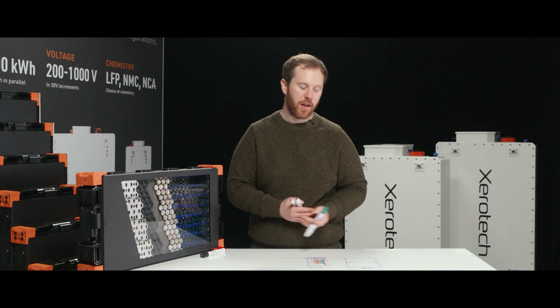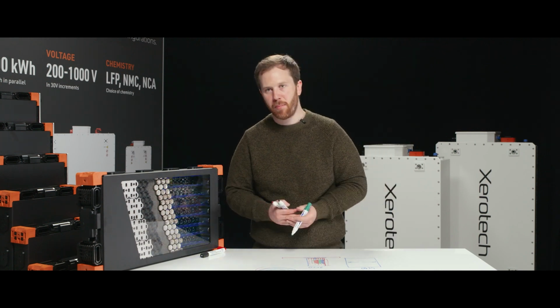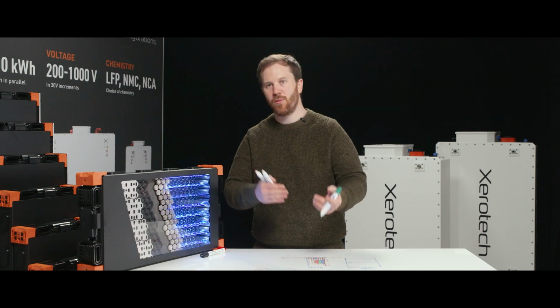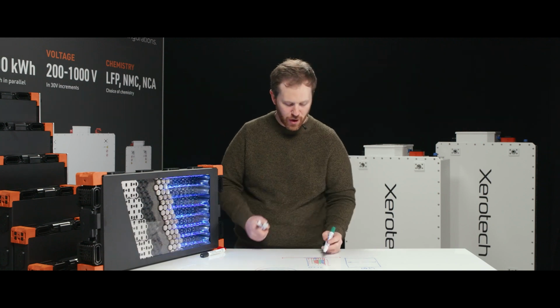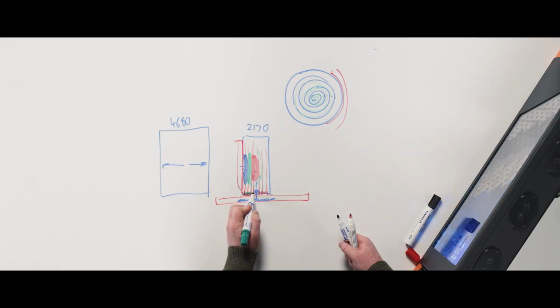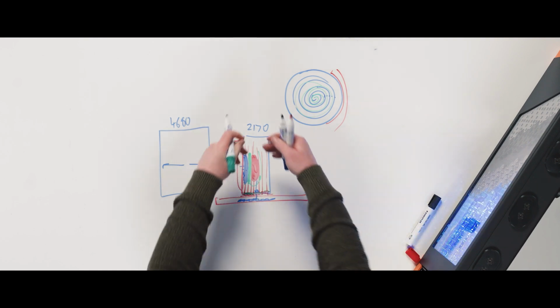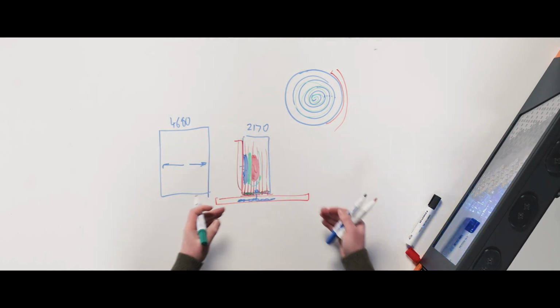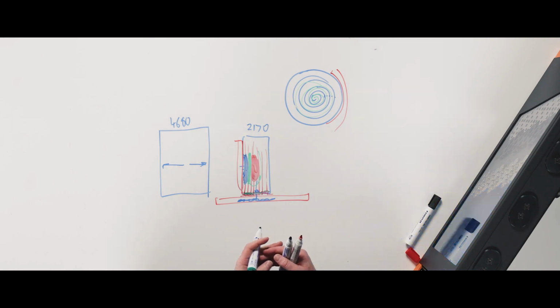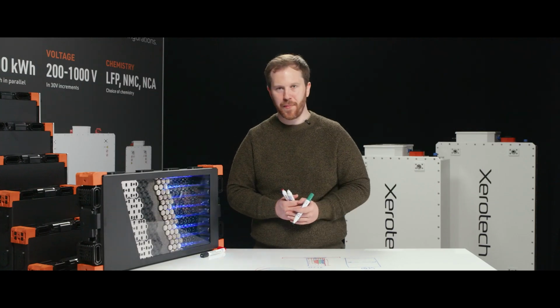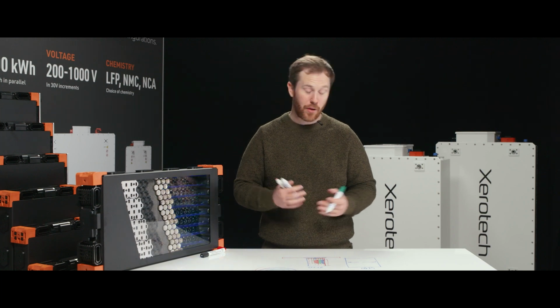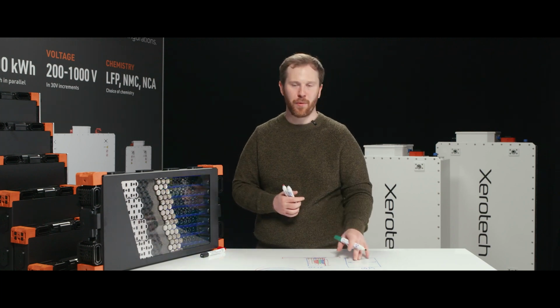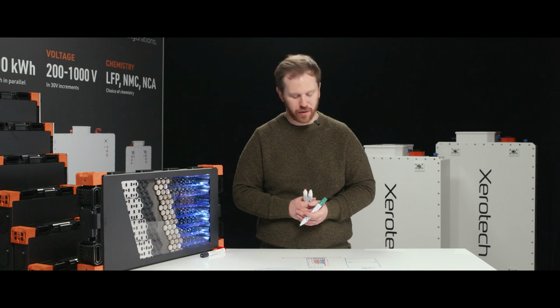Those of you in the industry would have heard of tabless battery cells, an invention Tesla and many others have deployed. What they're trying to do there is decrease the thermal resistance at the bottom of the cell to promote the heat transfer out of it, to make them more effective for sidewall cooling. But even still, an important fact that I point out even to my own engineers is that when you take the Tesla 4680 tabless design, they're still doing sidewall cooling. Now that might be for manufacturing reasons as opposed to performance reasons, but it's an interesting point nonetheless.